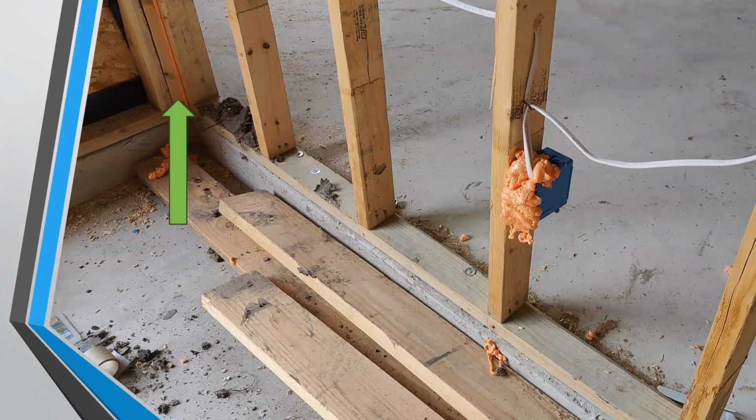Each interior and garage side electrical box must be sealed to limit air movement into the cavity. Also notice the corner of the garage here, they've also put poly seal there. It's a gap smaller than 1 inch, so they just poly sealed the corner. If that's overdone, it'll be scraped out by a screwdriver, and then it will just be left as unsealed.